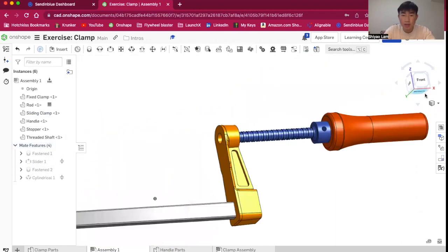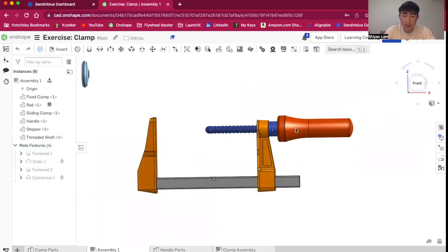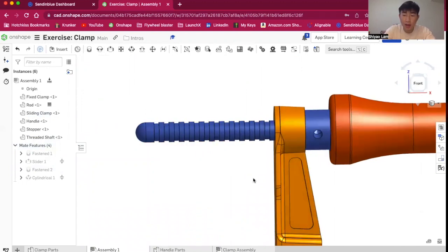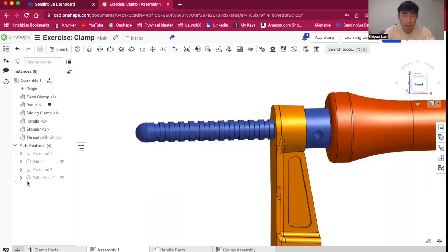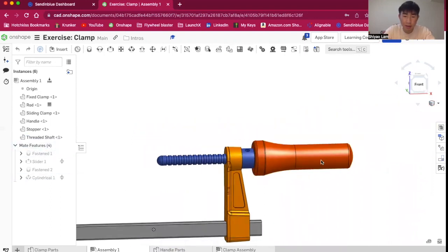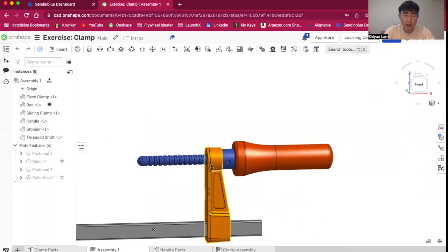100.52131. If you take a look now, if we try to slide this down, it stops right at that maximum point. So we just used the dimension tool to measure the horizontal distance from this line to this line. And afterwards, we added that as a constraint. So now it can no longer push through that part. It only slides through like this.